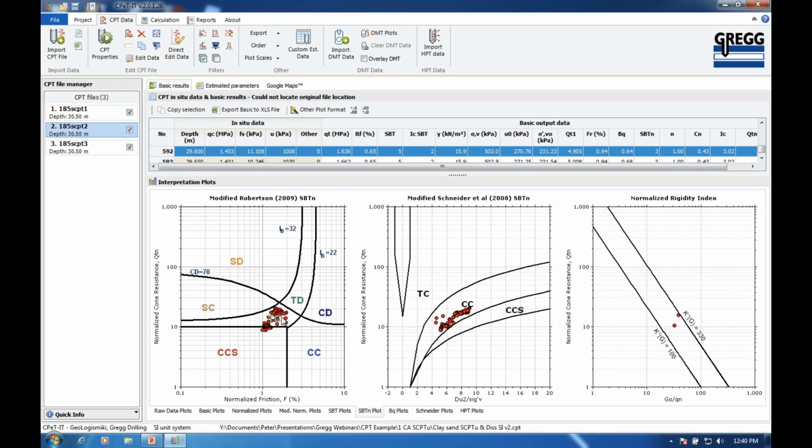It's plotting into the transitional zone, a more siltier transitional material, transitioning from either sand-like to clay-like. And certainly looking at the profile, and we'll look at the dissipation test, it is generally more clay-like, but it is siltier, so it's falling into that transitional clay-like material. And even on the pore pressure, it's still within the clay-like zone based on excess pore pressure, but it's a little stiffer.